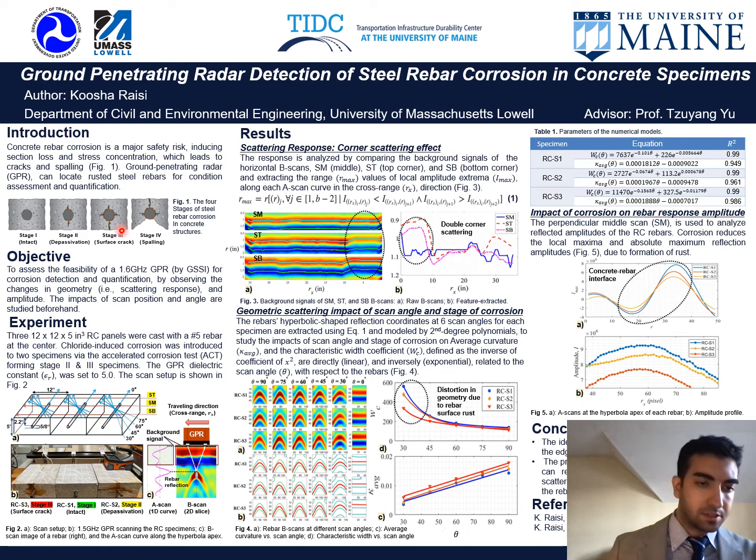So as you can see here, at stage 3 we have a surface crack along the length of the member in the middle on top of the rebar exactly, and at stage 2 they're very similar, except that we do not have any surface cracks. And stage 1, of course, for baseline, there is the intact specimen.